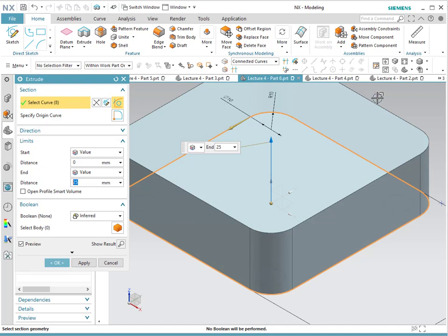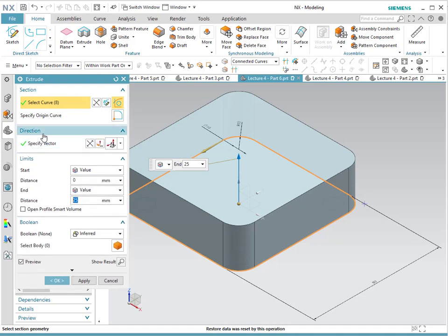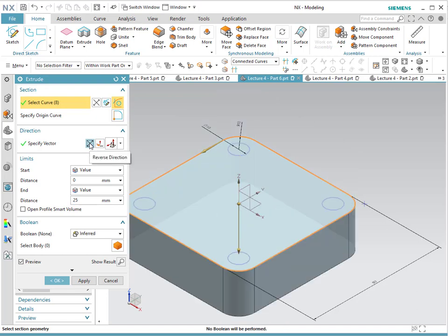If it doesn't, most likely it means that the path that you selected is not closed. Therefore, you need to revise your sketch. So I'm going to make this a little bit bigger. Excellent. So now what we're going to see is that we have a three-dimensional solid. Notice by default it gives us that the sketch goes upwards. If you need it to go downwards instead, you simply open the direction choices and switch it, either going up or going down depending on what you would like.